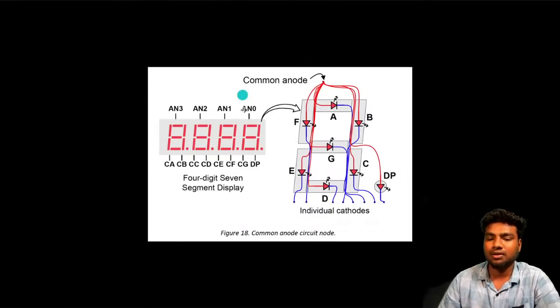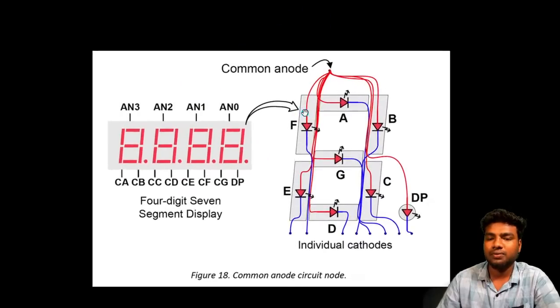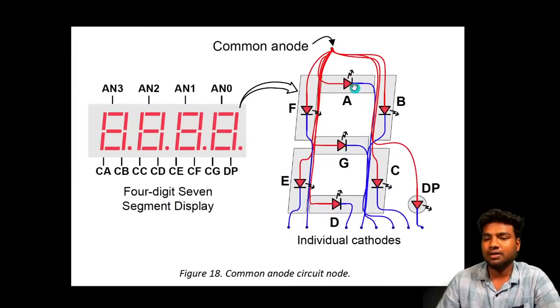So this is the circuit diagram for that 7 segment. You can see inside a 7 segment, this is the structure. Here A has one LED and B has one LED. You can see this LED symbol. It has 1 2 3 4 5 6 7 LEDs and also DP. DP means the dot point. This dot point is called DP, and it is also an LED.